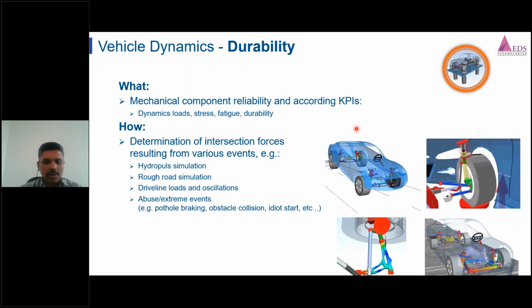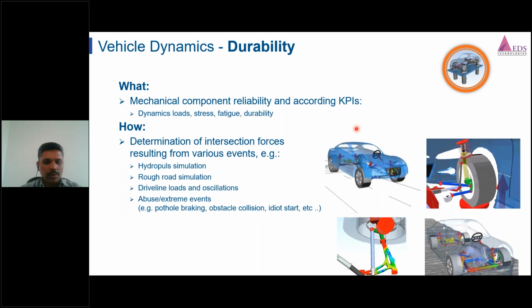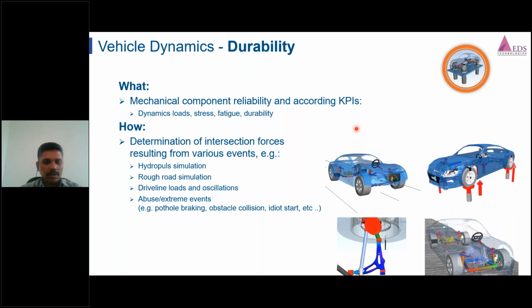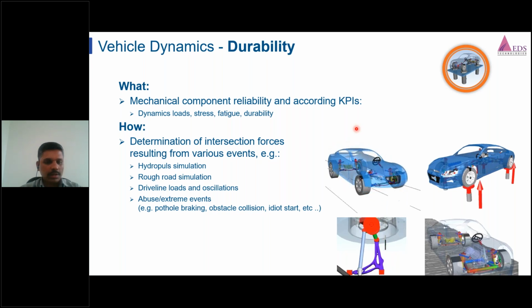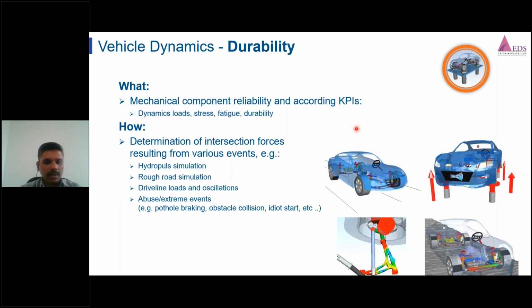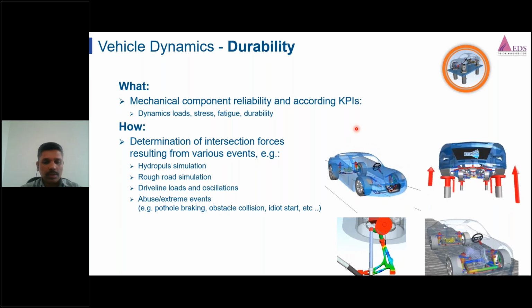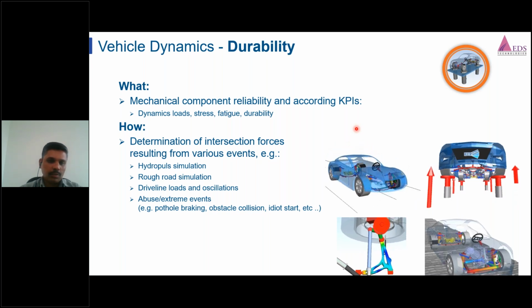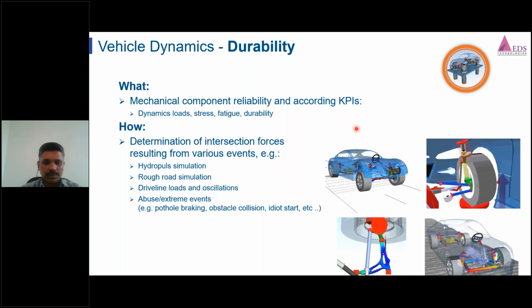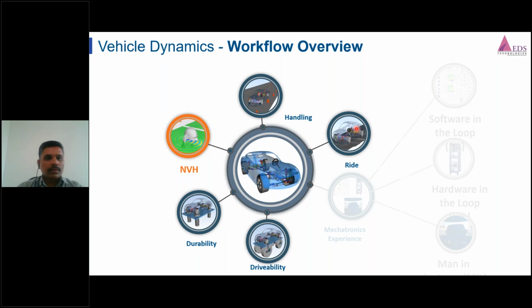For instance, maneuvers like pothole braking or even obstacle collision between the suspension components and obstacles might be simulation scenarios. In this, we can get the stress results from the post processing. It is possible inside of Simpack, and we can provide those stress results as an input to the durability codes. So next workflow is the NVH.